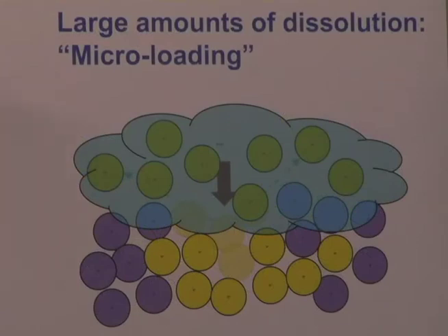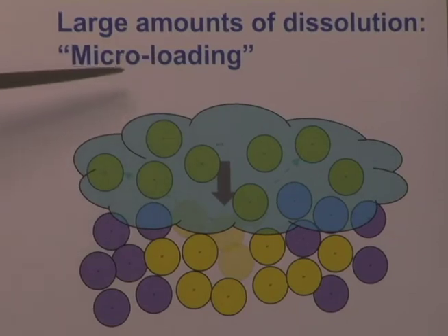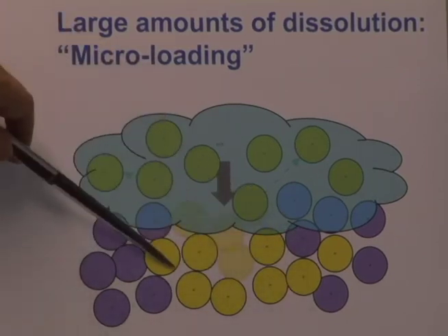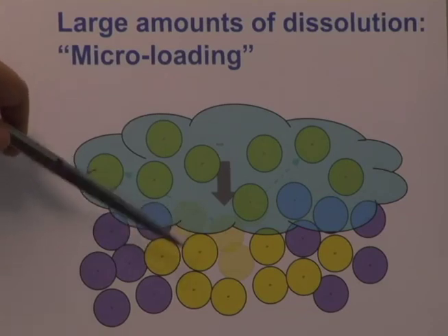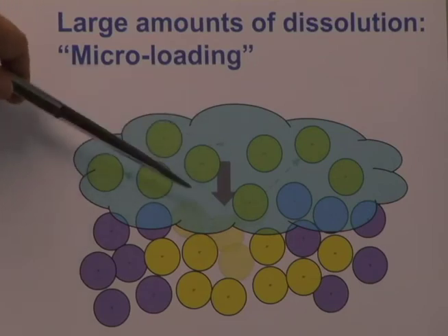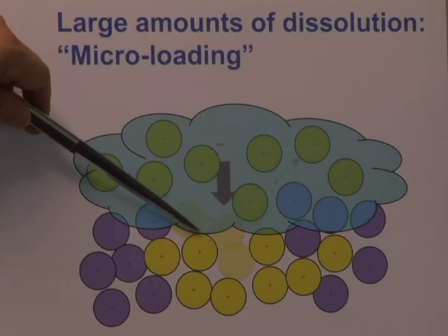That being said, there's another key nonlinearity to talk about, which serves to seemingly counterintuitively slow the dissolution rate down as the resist exposure gets larger. We call that microloading. Consider what happens if we encounter a large area of reacted resist. All the resist will, in principle, develop very quickly into solution. But what I failed to mention is that the solvent-resist interface behaves very similarly to a gel and has relatively high viscosity compared to the bulk solution.